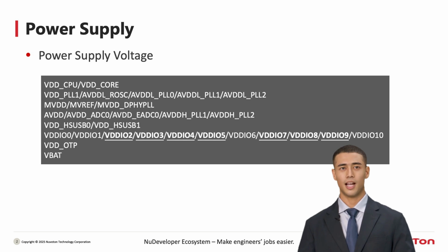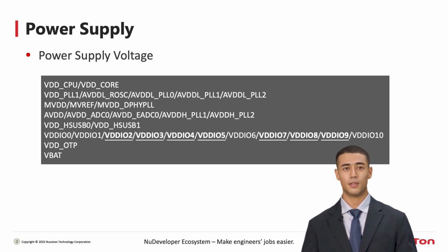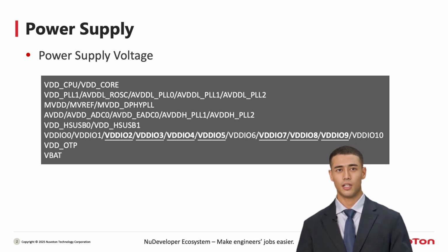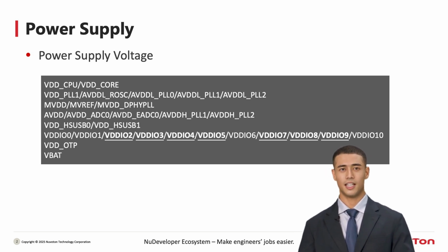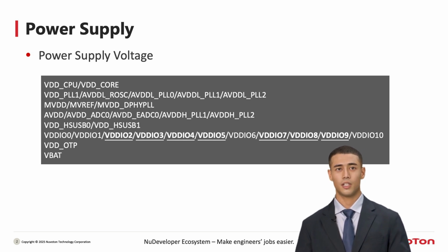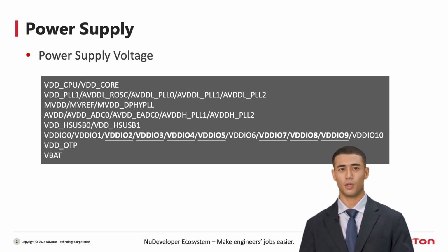The internal power supplies of the MA35D series chips are independent units. Therefore, whether or not certain functions of the chip are used, such as RTC, ADC, etc., all related power pins of the chip, such as VBAT, AVDD, must be connected to the corresponding voltage levels and must not be left floating. Some module I/O levels of the chip support 1.8 volts or 3.3 volts. When designing the schematic, match the I/O levels according to the peripheral devices connected.